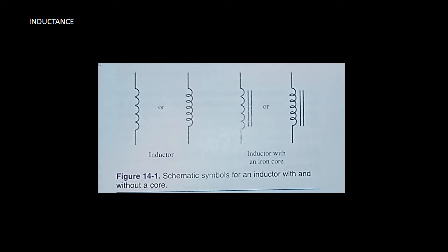A coil connected to a source of direct current builds up a magnetic field when the circuit is closed. The expanding magnetic field cutting across the coil windings induces a counter EMF. This voltage opposes the source voltage and opposes the rise in current. When the current reaches its maximum value, there is no further change in the current. Consequently, there is no longer an induced counter EMF.